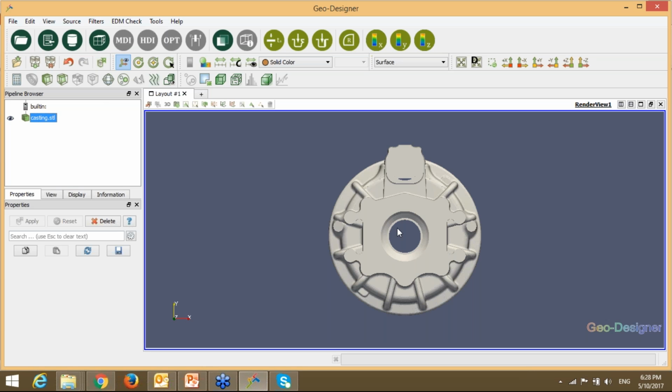The reason is that when you try to do reverse engineering of an existing casting part or gating system design, you have already invested in your pattern. You already have your tool and pattern available, and it is difficult to change things like the location of your riser, neck size, the location of the sleeve, or the location of the inlet or feeder. That's why it is very difficult to change once you make a pattern. These things are very costly and difficult. So here we can do this upfront, which could save lots of cost later on.